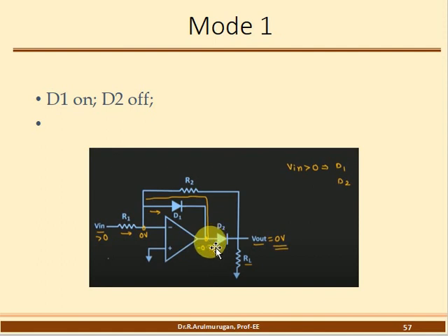If there were no diode, the current would be negative, so the voltage is 0. There is a drop across the diode of minus 0.7 volts. Because of that, the signal does not reach here, and the output maintains 0 voltage.